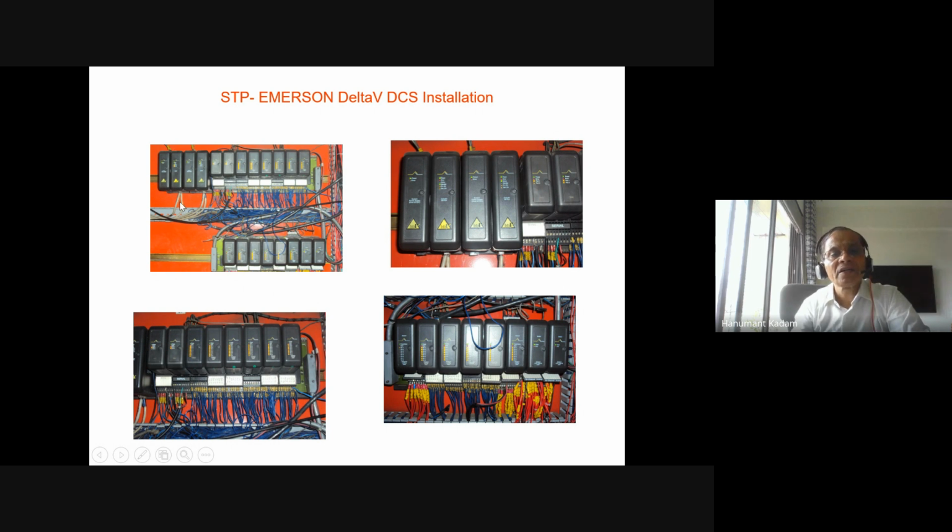And you can see below the controller two wires are there, meaning these are network wires. And why two? One is the primary high speed ethernet cable, and the secondary is another. Only the color of the connector cap differs here, so you can identify the primary and secondary cable.